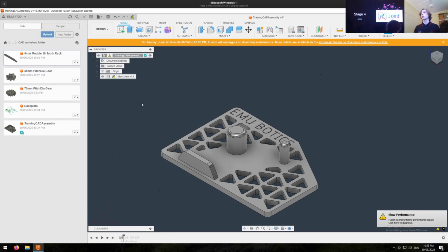And what we're going to do is make sure that we pin the first component in our timeline. No matter what assembly you're doing, every single assembly file should have the first component pinned. And generally, you should make sure that your first component is a significant one. You don't just want a spacer or something to be your first component. You want it to be like a chassis rail.